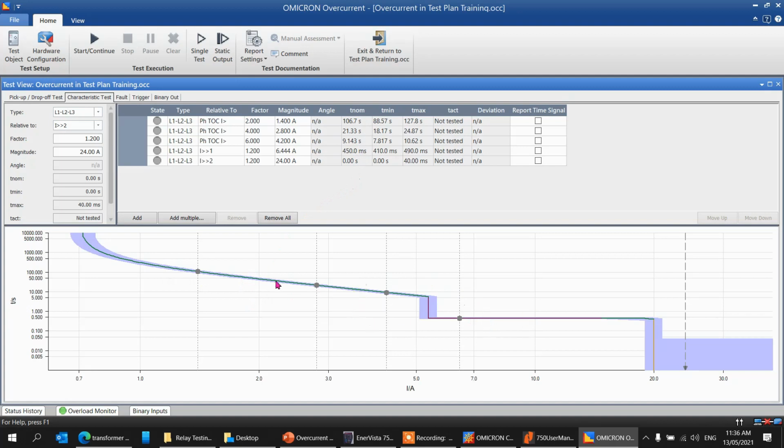I just want to share what I always do there. So normally on the third point here, I use as reference the first stage of instantaneous and then less 5%. So that I can show that the dot will be somewhere here, close to the edge. And also I'm doing that here, where I use the reference of first stage of instantaneous and I add 5% to that here. So you can see the transition from the curve going to the instantaneous strip. But it's up to you.